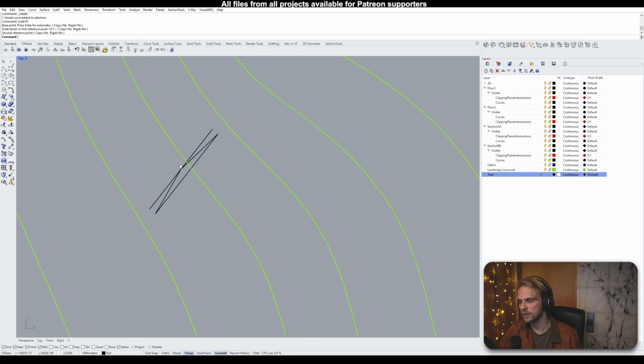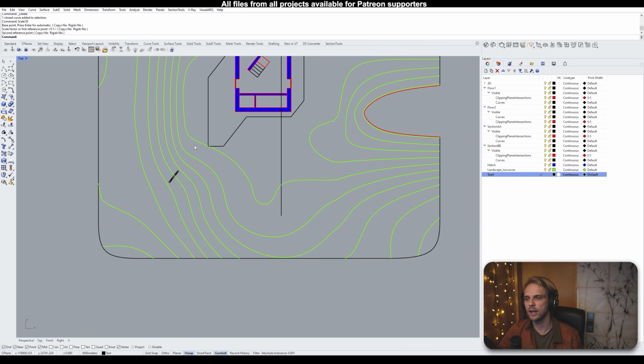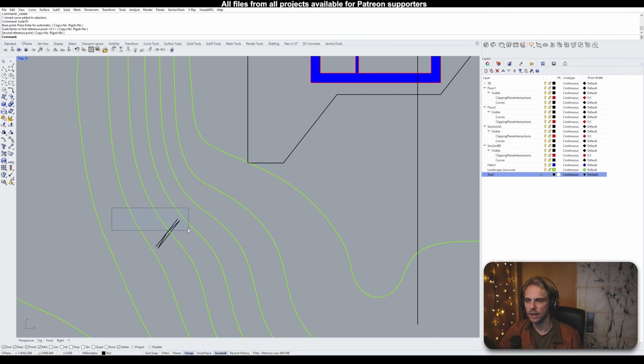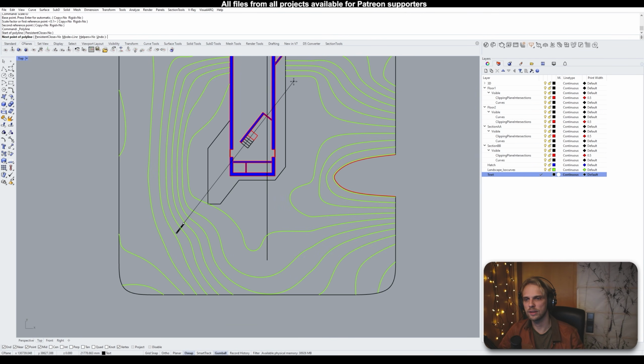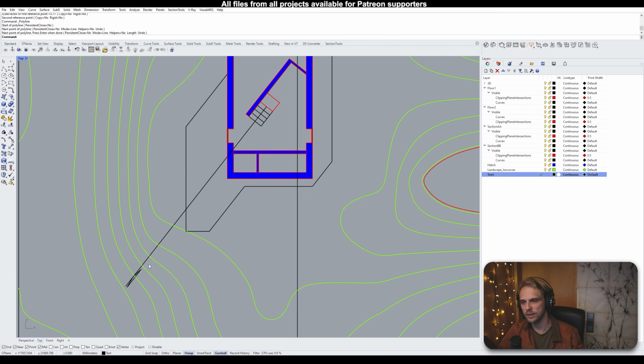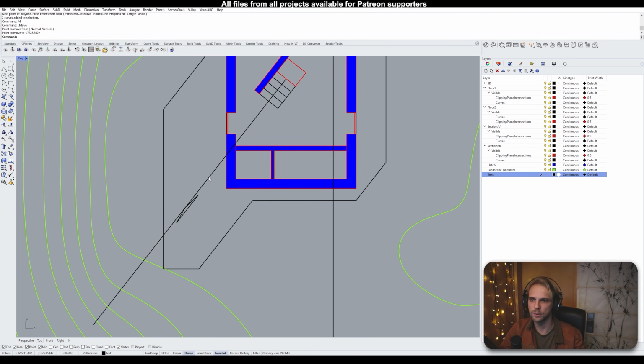And that's a nice little triangle to mark out where the section is taking place. I think we should move it closer to, let's get it back on track. It went right through the middle of the staircase, so it's easy to create a line like so and just move it closer to the building. Let's see, somewhere here.